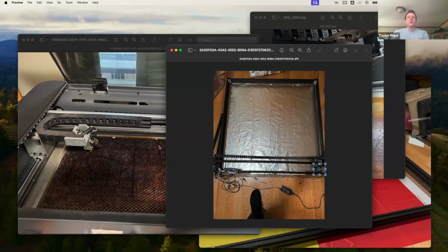Fiber lasers are often used as marking lasers, especially because they can be very precise and can even be tuned to the point where if you use them with certain metals, they can oxidize at different powers to cause different color effects. This can result in being able to even do color markings with a marking laser, as well as being able to do depth-based engravings by engraving away some of the metal materials.